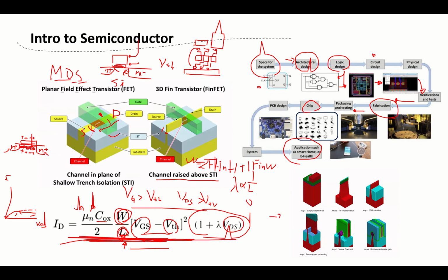Then it's the process. How do we fabricate the chips? This is only an overview, but there will be more detail later. So first, here we call it OD. So we implement the N well and P well regions. Then we start making the fin. So in this way, we do lithography and etching to etch out the fin over here. Then we use CVD to fill with STI. That's to isolate the different devices.